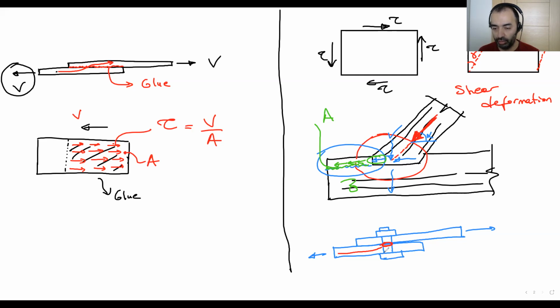If it works, yes, we can transfer it to the other plate. It works means if the calculated shear stress is less than the bolt's allowable shear stress, that's okay. It transfers all the load to the upper portion. If not, it doesn't work. We have to increase the number of bolts, or we have to increase the size of the bolt to get a higher area.